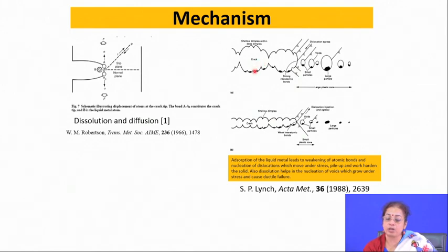Where there is no liquid metal, the typical mechanism of fracture is nucleation and growth of dislocations. In the liquid metal case the same mechanism occurs, but the plastic zone width is much lower, so a small plastic zone forms.